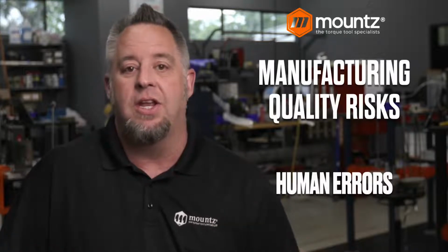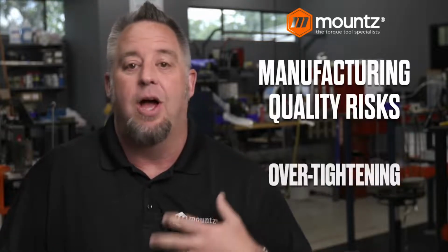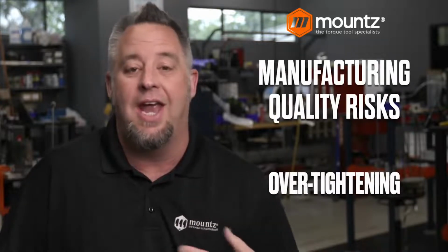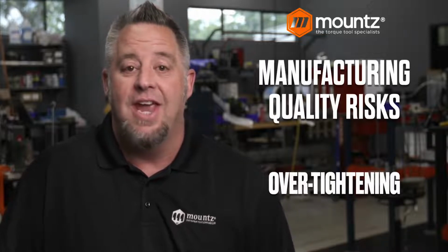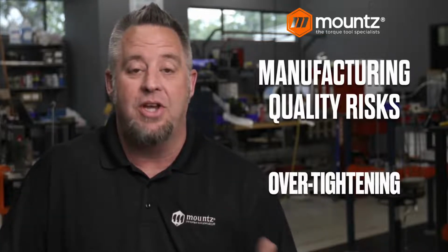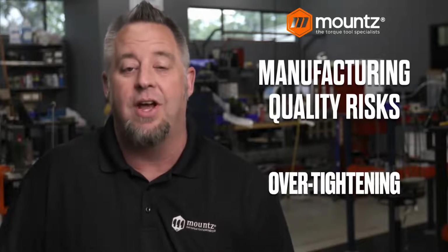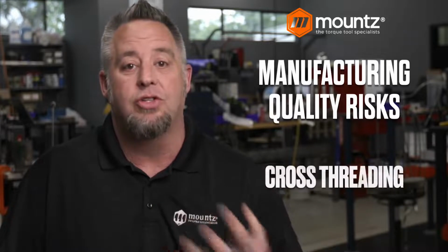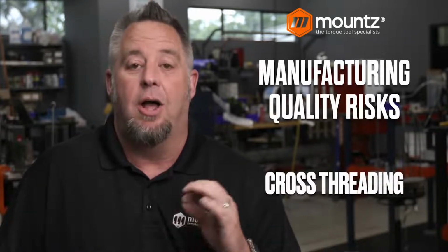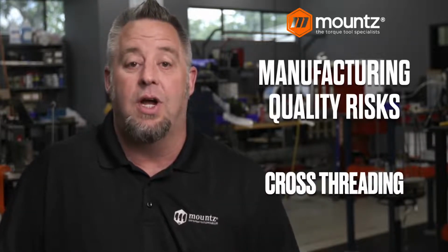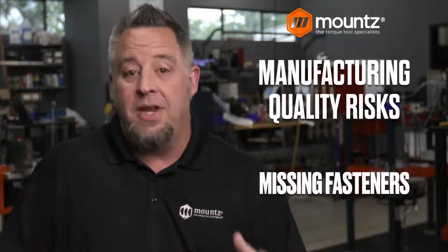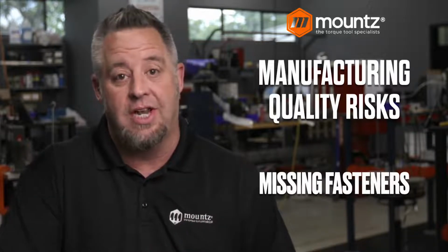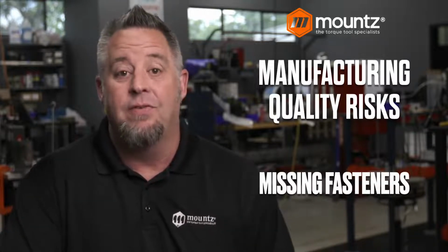Often we begin these sessions by talking about the different types of risks that are associated with the quality and the manufacturing process. We always mention over-tightening or over-torquing fasteners, as well as under-torquing fasteners. We also deal with cross-threading, these types of errors that do not allow us to get the correct clamping force that we need for our components.